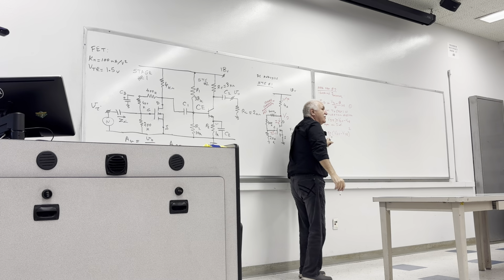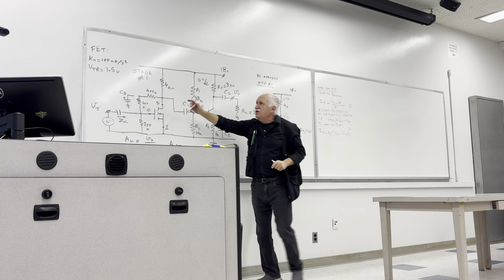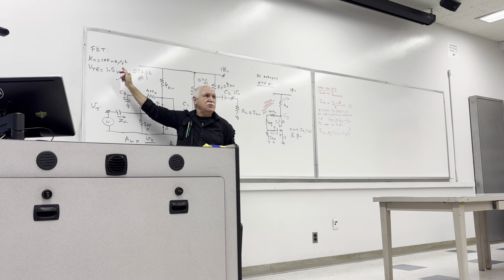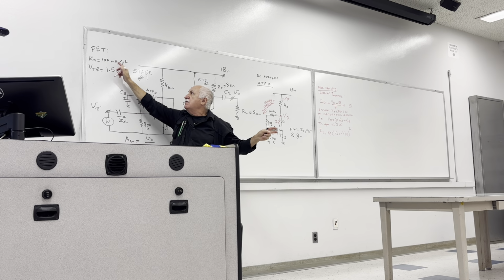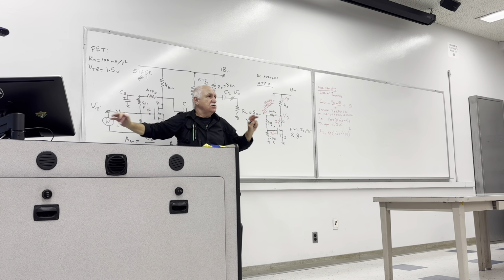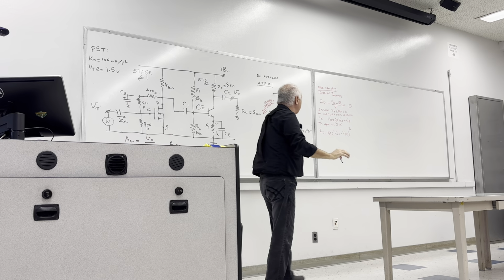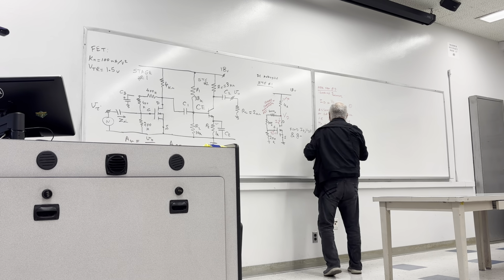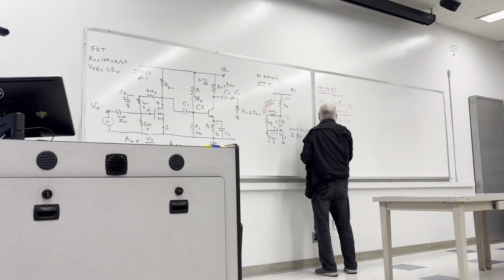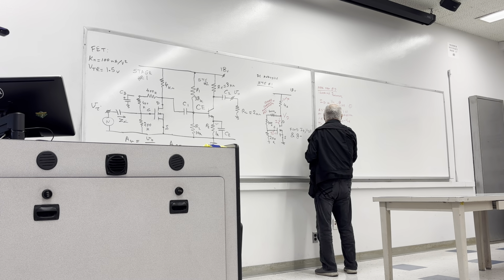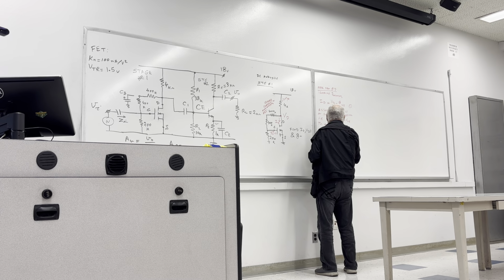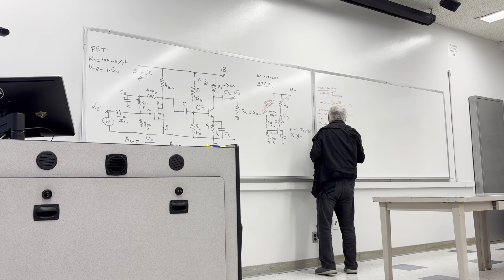So we substitute the values. It's given in the milliamp per volt squared, stick to it. Milliamp, volt squared, volt, kilo ohms, we keep everything in that scale. So we will have ID equal to 50 multiplied by VGS minus 1.5 squared.